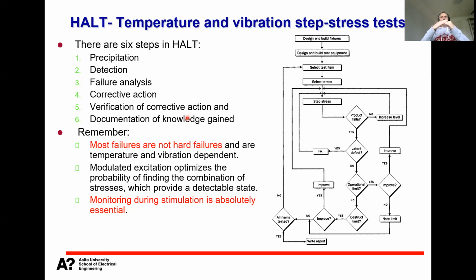If this is a power connector, the system loses power, but it's not something that permanently fails. That's why we should always, if possible, monitor all the time during the simulation. Then you would really see what the hard, permanent failures are, in what situation the failure occurred, and then you can take corrective actions.